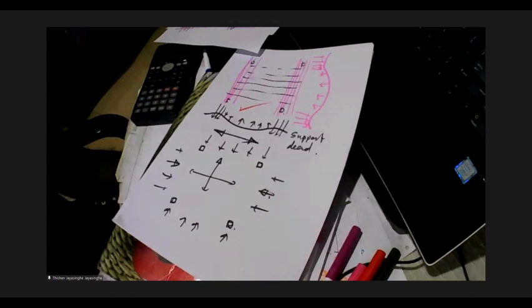So basically, we are converting the two-way slab system to a one-way system. Because it's a flat slab, which is supposed to span in both directions. But in the case of PT slabs, we simply convert it to a one-way system, where the load transfer takes place only in one direction. And then we check the stresses. Okay. So we see how this can be done.